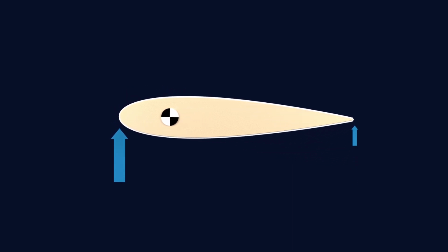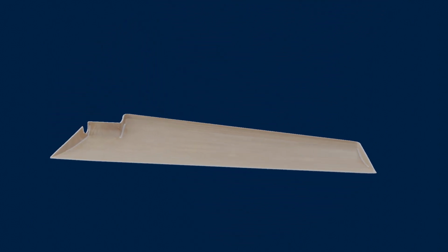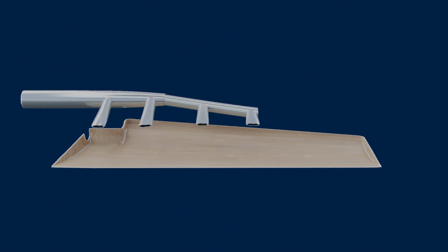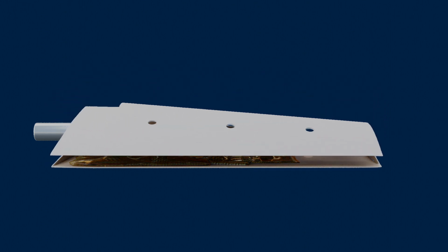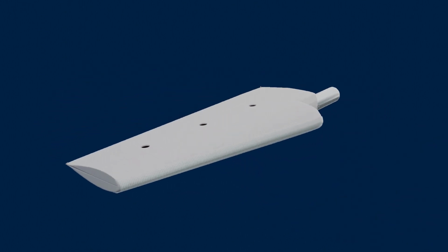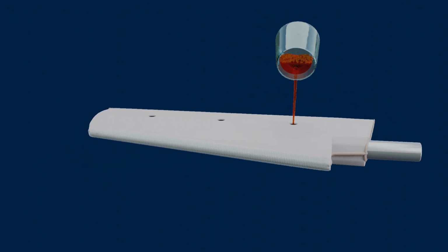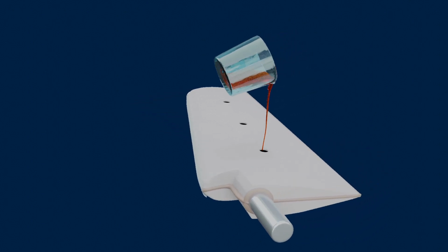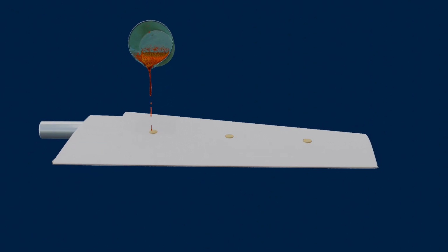To understand why the skin cracked, let's first look at how the rudder was originally put together. The rudder was constructed by first laminating the two separate halves of the outer skin. First, the port side was laid down, the shaft with the webbing added, and then glassed in place. Next, the starboard side was added and the seams sealed. The factory then poured liquid polyurethane foam through 3 holes opened on the starboard side. Once the foam expanded and cured, those holes were sealed and the exterior finished.